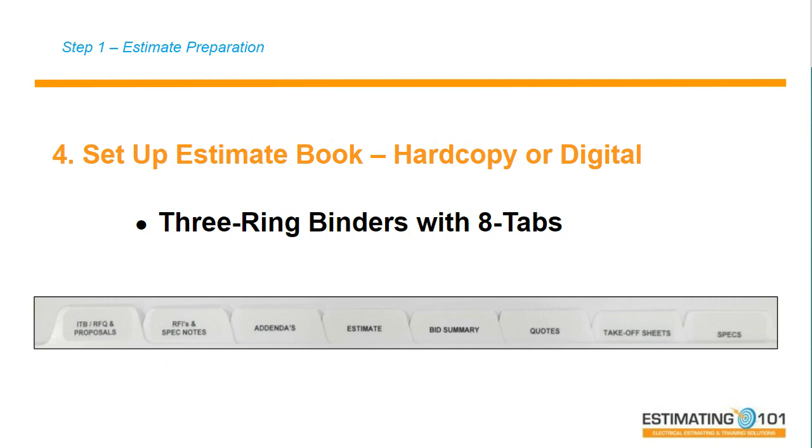If I average 15 feet for my branch wiring on all of my lights and all of my receptacles, but in reality it was 18 feet. Well, you think that 3 feet is not a whole lot, but 3 feet of 15 feet is 20%. So now you're going to be 20% short on all of the branch wiring, all of the lighting circuits, all of the branch receptacle circuits, and everything you averaged.